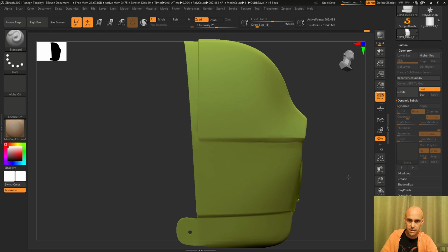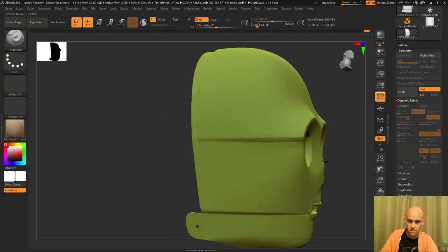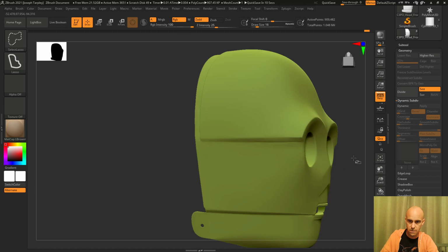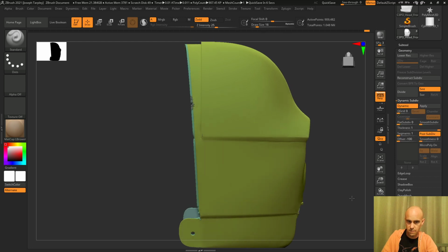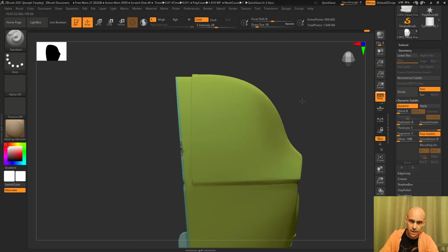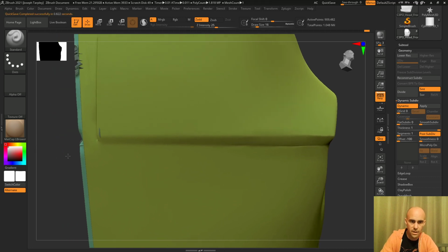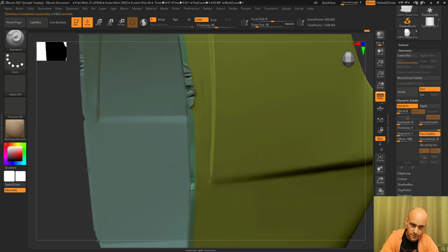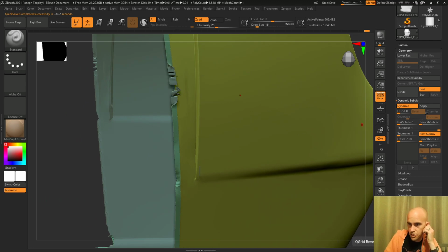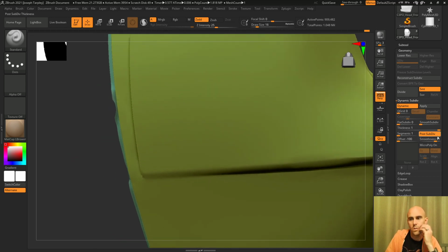Okay, so got that weird edge here. Let's see. All right, delete hidden. Okay. Still got a little booger on the edge right there. All right. How do I want to change this? So sometimes if you change the smoothness on offset, sometimes it'll fix that. It's a little weird. There's definitely some floating geometry kind of going on out here that I don't want.